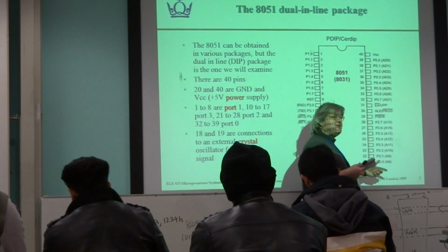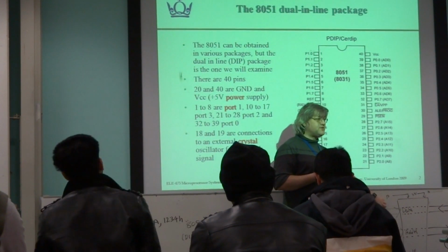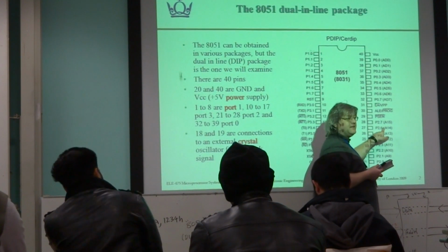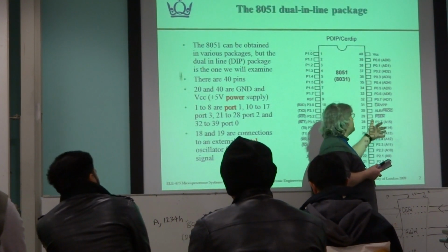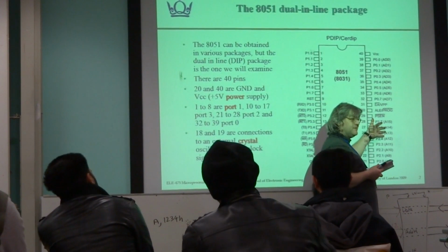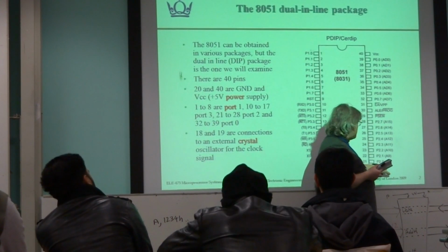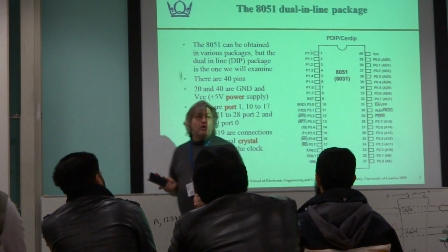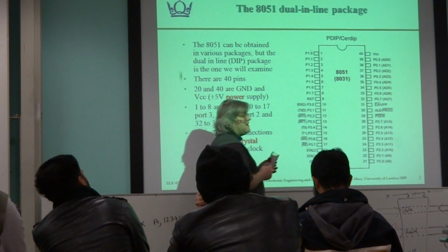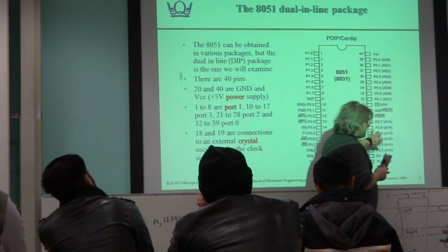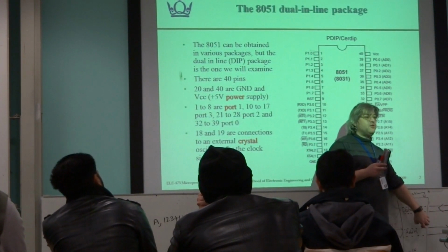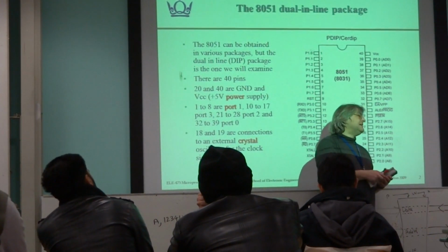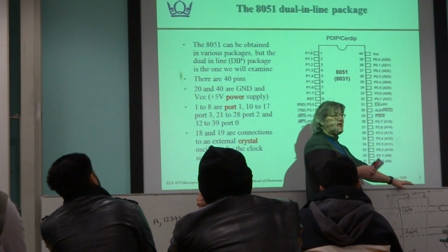That means when port 2 is being used in this way, with external memory, that pin is going to become the A15 line, that's the A14 line, and so on. The microcontroller will assume you've wired it up that way. So if you decide, actually that's going to become the A15 line, and that's going to be the A8 line, it's all going to go extremely horribly wrong. This use of external memory assumes it's wired up in precisely the way I've shown. There's no negotiation there. It's that way or it doesn't work.